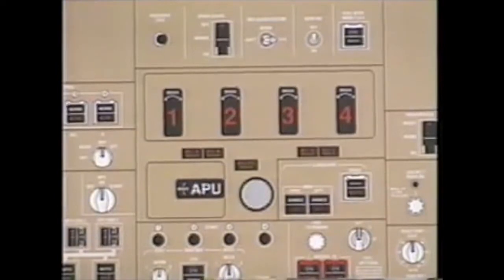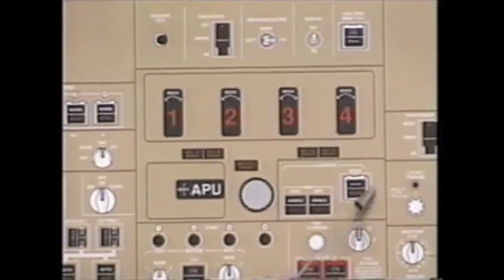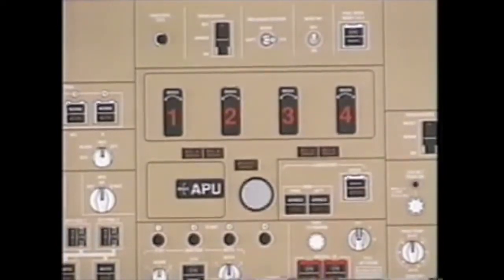In the event of a lower cargo fire, we call for the QRC. The QRC is going to have us arm the appropriate forward or aft button and then press the discharge. Please note it can take up to 30 seconds for the discharge light in the switch to illuminate, indicating that bottles A and B have discharged. Bottles A and B will give you an initial 30 minutes of protection. In 30 minutes, or landing, whichever occurs first, bottles C and D will then meter in over the next 2 hours and 30 minutes for a total protection time of 3 hours and 15 minutes.